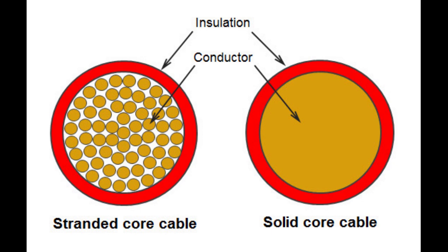An interesting note is, electricity tends to flow around the surface, or skin, of the metal conductor wires. So if there are a lot of smaller wires making up a larger bundle, then electricity will flow better, as there is more surface area. Stranded wire is made up of lots of finer wires that make up a larger gauge of wire. This makes stranded wire more efficient and often more practical because of its flexibility.